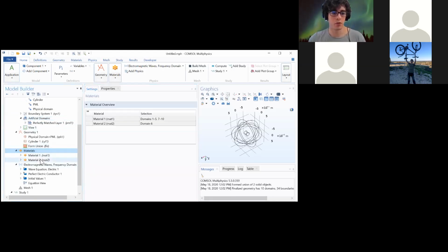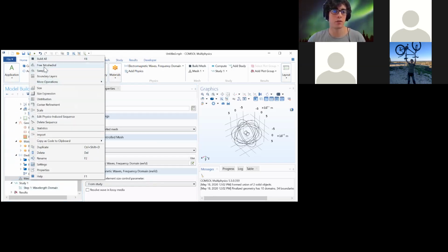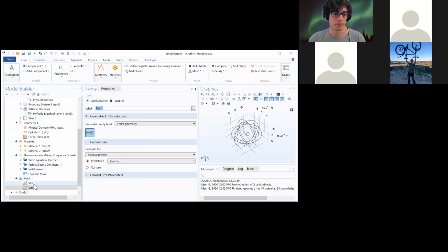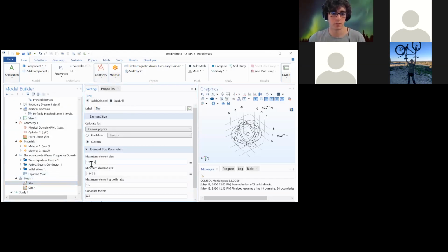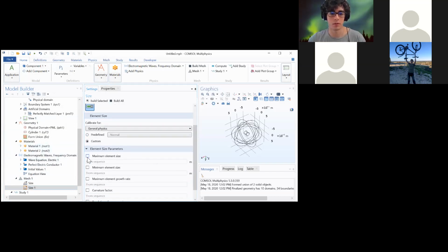Next, we have forces, we have materials, everything. We'll just define very fast also a mesh. We just set the mesh to be at least a fifth of the wavelength. And for the particle, it's the same, but just taking into consideration that the refractive index is higher.